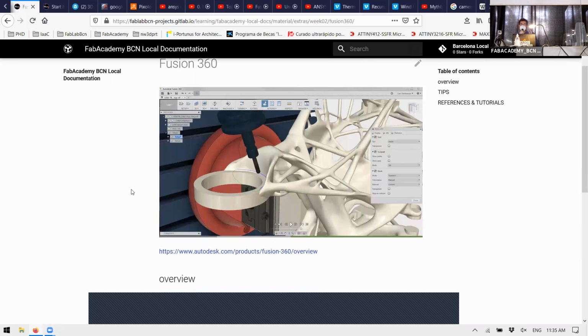What you should never try to do is transform a mesh into a NURBS, because you will not get a defined model. The same happens when you translate a raster to a vector: you are not getting a perfect image as a vector. But from a NURBS to a mesh is way easier.